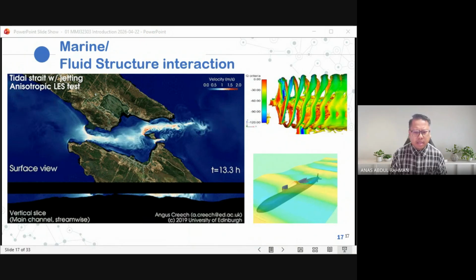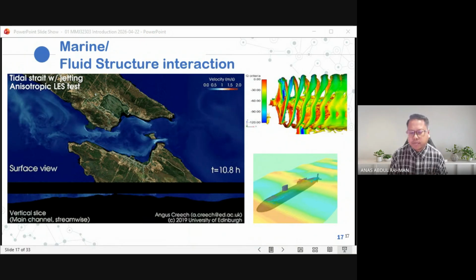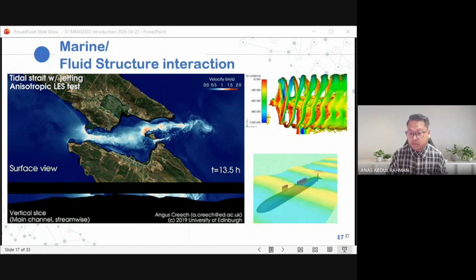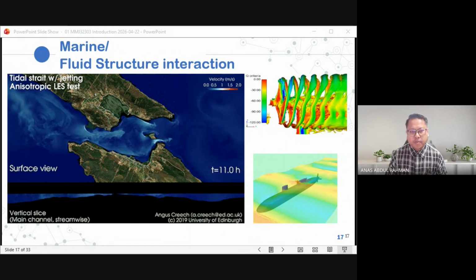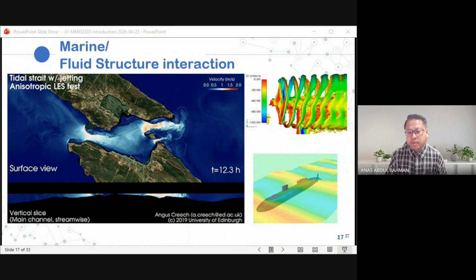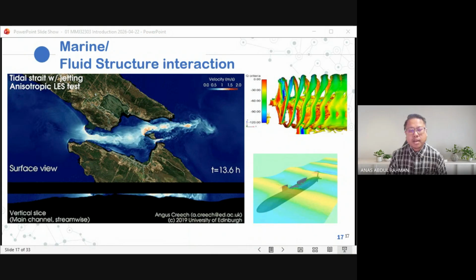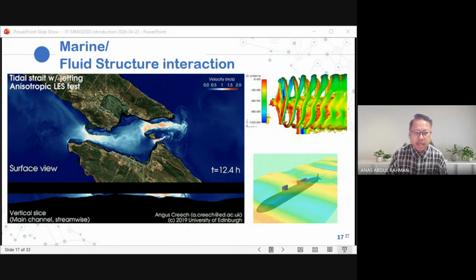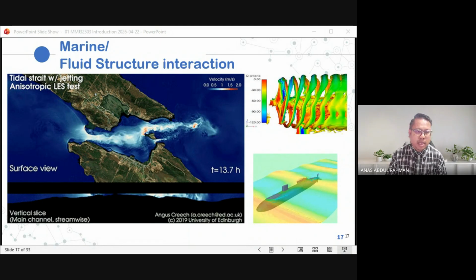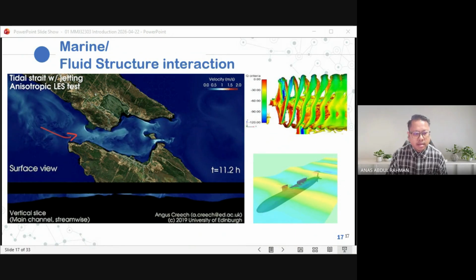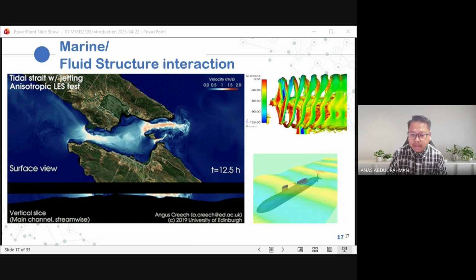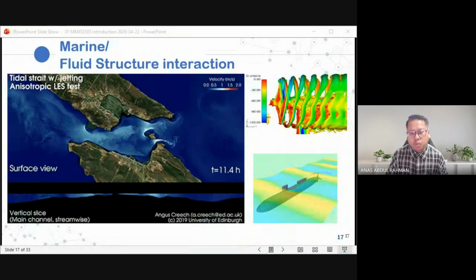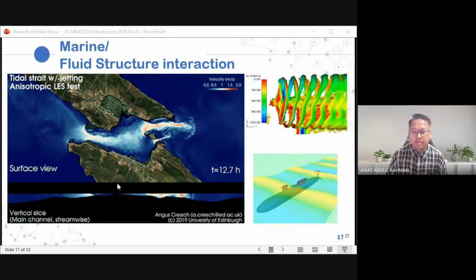Instead of conducting a time-consuming and expensive experimental procedure, we can now use CFD to see the phenomena, and in research, for example, to identify the location where we can deploy a tidal turbine for energy extraction. But again, remember, garbage in, garbage out. In order for us to get a simulation output like this, a clear, high quality, and dependable result, you must know what you're doing and what the input basically represents.